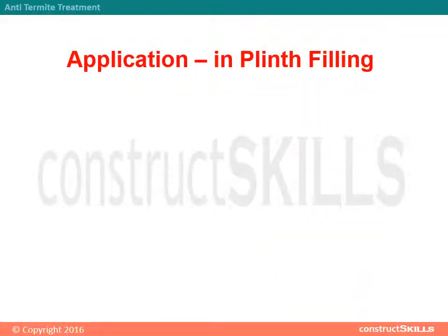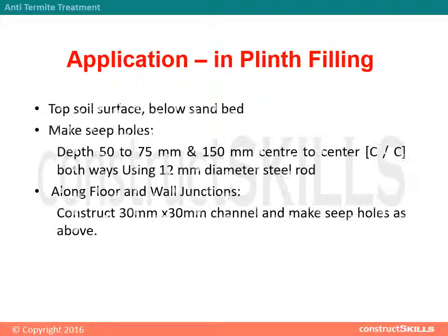Application in plinth filling: applied to the topsoil surface and below the sand bed. Make seep holes of depth 50 to 75 mm at 150 mm center-to-center intervals both ways using a 12 mm diameter steel rod. Along floor and wall junctions, a 30 mm by 30 mm channel is to be constructed, and seep holes made as above.